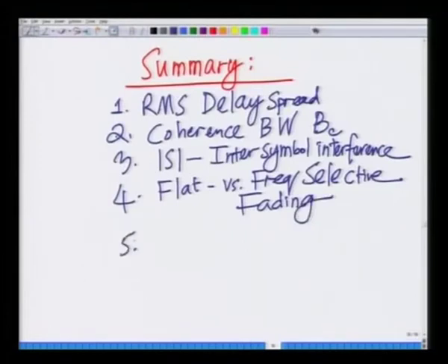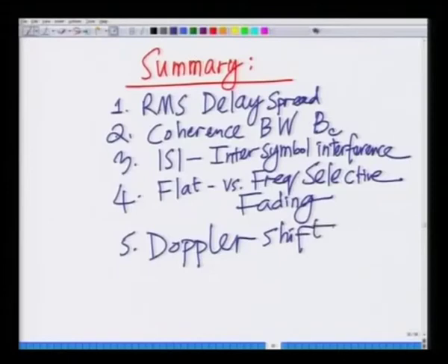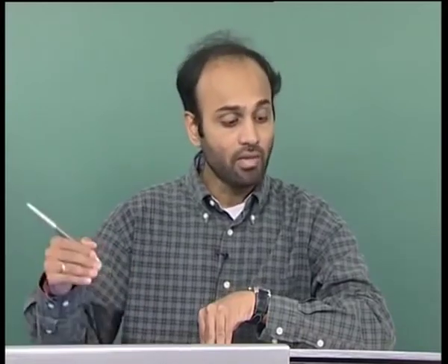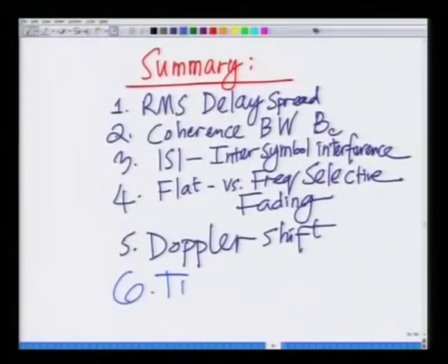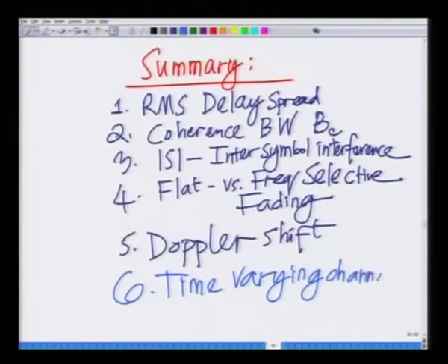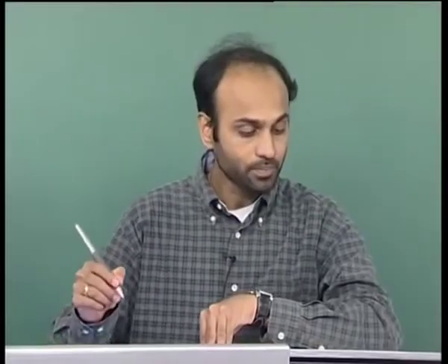Then we introduced the notion of the Doppler shift arising from a velocity. If a mobile is moving towards or away from the base station, that results in a Doppler frequency shift. We said this in turn results in something important. This results in a time varying channel.